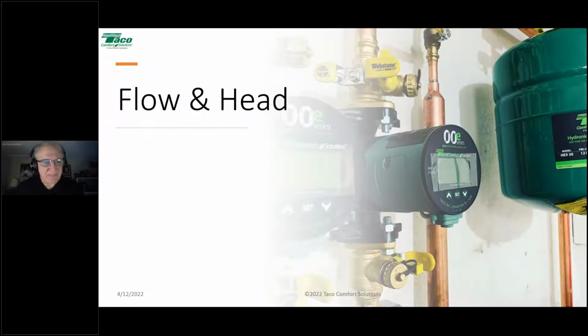I've been a long time proponent of the notion that overpumping is a critical problem in the residential hydronics industry. The reason it's a critical problem is that overpumping limits the overall efficiency of the system, but it also has no noticeable symptom, meaning the system's going to work. You overpump, you're still going to deliver BTUs. Nobody's going to freeze to death and call you up and blame you. And usually that's the number one hurdle we're worried about in a residential hydronic system.